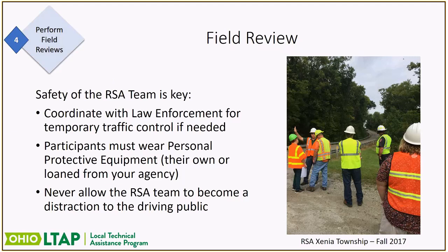We make sure that everybody knows they have to wear personal protective equipment. They need to have a hard hat, a vest, proper footwear to be out alongside the road. Here at LTAP, we have a complete set for a team if you would need to borrow it, but a lot of them are doing this on a daily basis or have availability to bring their own equipment with them. And another key is never ever put your team in an area where they can become a distraction to the driving public, because the last thing we want to do when we're out doing a road safety audit is to cause another crash to happen.